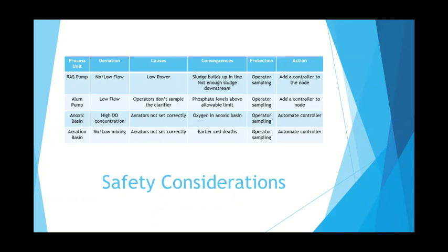High levels of oxygen will detrimentally affect the anoxic basin as the bacteria will revert to a more desirable reaction. This can lead to problems downstream involving the quantity of cells. Some of the cells die while in the anoxic basin. If the aerobic reaction is done instead of the anaerobic, there is no stress to kill the cells off. The larger volume of cells moving through the system will inundate the secondary clarifier.